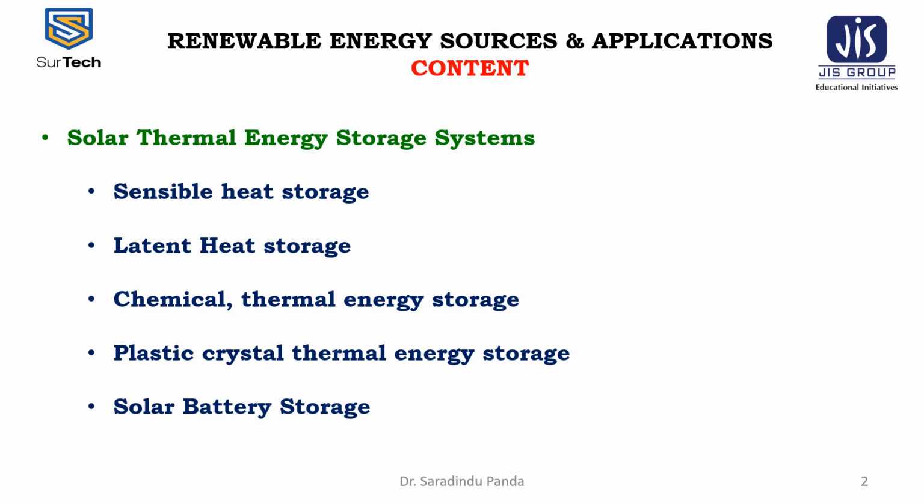The former is usually applied for the domestic hot water supply. It is usually stored in small hot water tanks when used for single family houses, or in large underground containers for large housing projects with 100 and more apartments. The high temperature heat is applied for all sorts of power processes and in chemical engineering. In these cases, heavily insulated tanks, often pressurized, will be used.